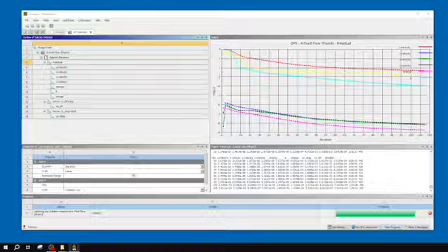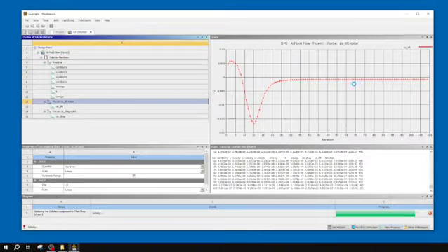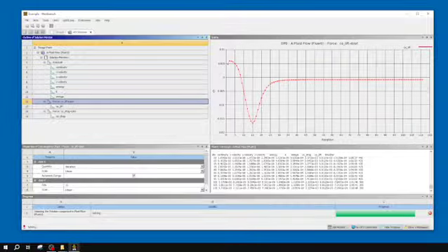As you can see in my residuals, it's getting very flat. It's still decreasing a little bit, but it's rather flat out here. If I go over to my coefficient of lift, we can see very little change, both in the plot, but also as I look down at these numbers, it's the fourth-ish decimal place that's been changing these past couple iterations, right? 7979 times 10 to the fourth.